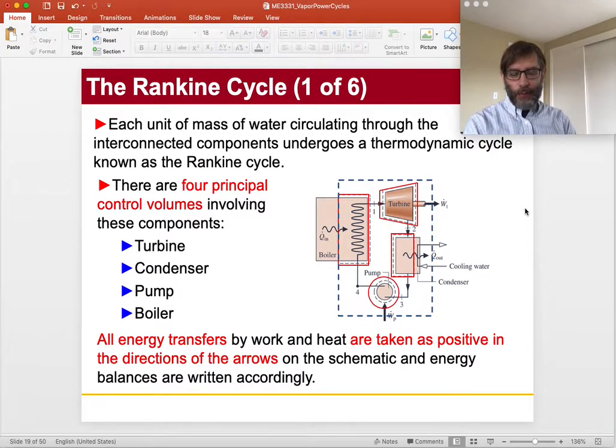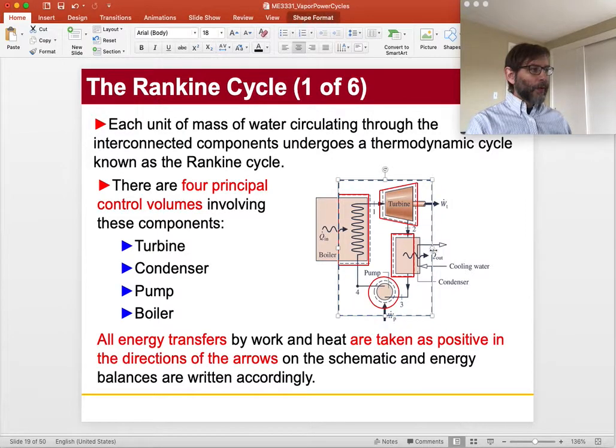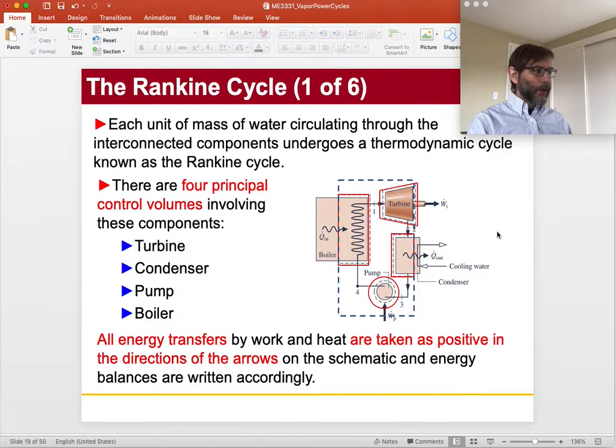So the overall system can be a control volume, which is what we do when we have Q in and Q out. Q out is sort of like this, right? So Q out, don't worry about what's coming in and out of the control volume in terms of fluids. If I can make this really close to the boundary of the turbine, that'd be good. There we go, something like that, right? So you have Q out, you have Q in, you have the turbine work, you have the pump work. So you only have the works and heats going through this system, which is what I'm talking about. Of course, there's probably heat loss as well, but we're not going to talk about that.